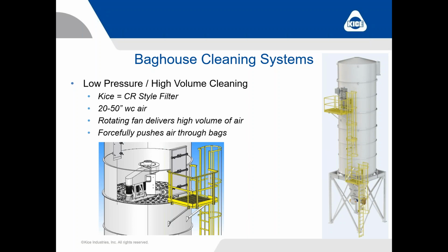Now, this is at much lower pressure than the past two types we talked about, but a much higher volume of air. And that continual downward rush of air is what helps us keep the bags clean, knock the dust off, have it taken away by the airlock at the bottom, and help extend our bag life.